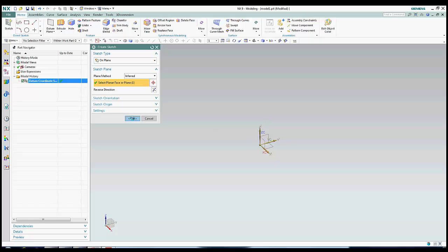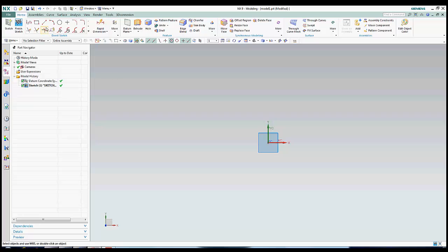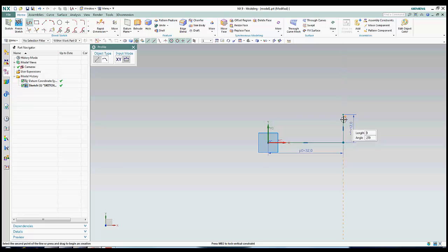I'm going to set the dimensions of the first few lines as I create them. For the rest of the sketch, I will create rough lines so that I can go back and constrain them using geometric constraints later. As you can see, I simply need to type in my desired length before I set the line to make it fully constrained upon completion.